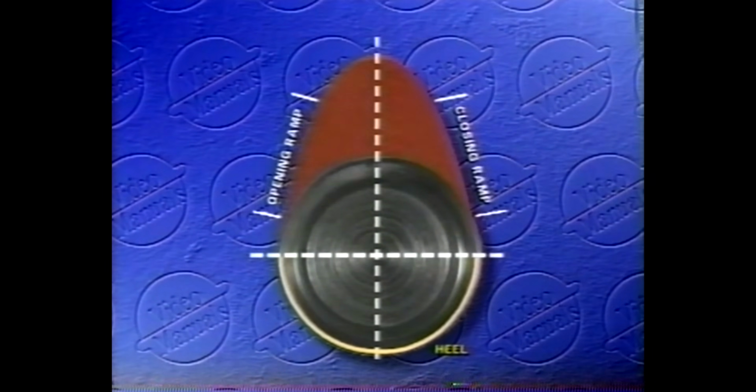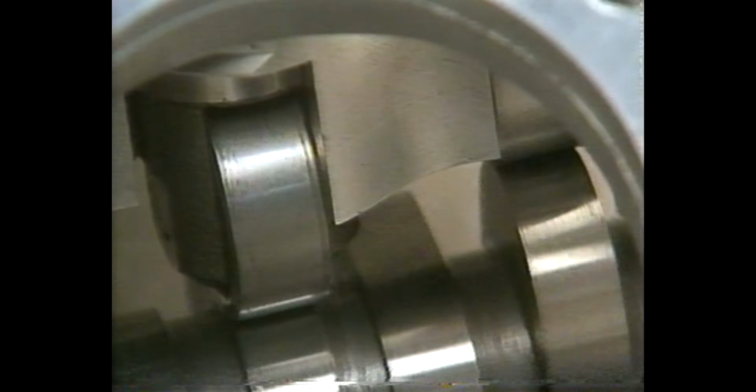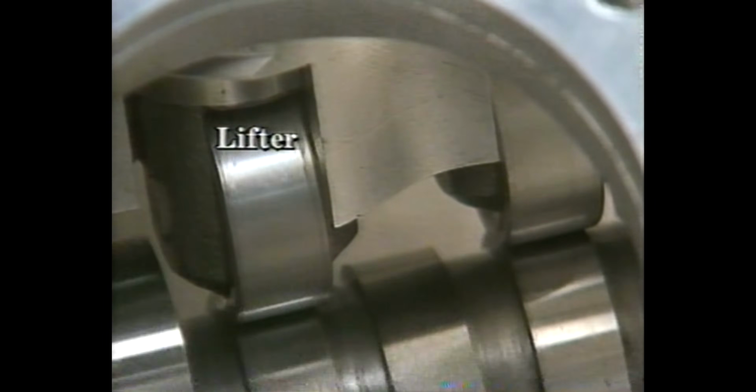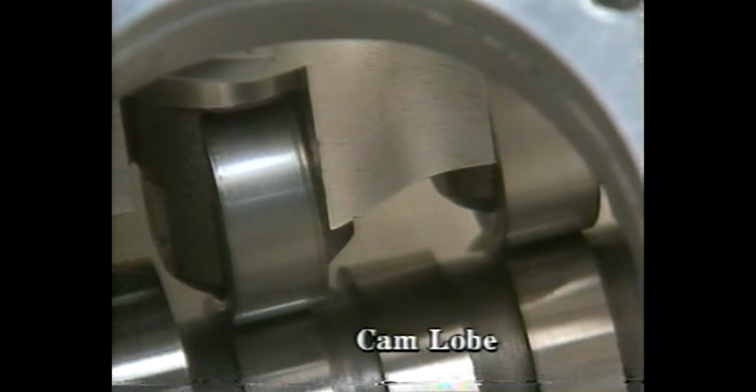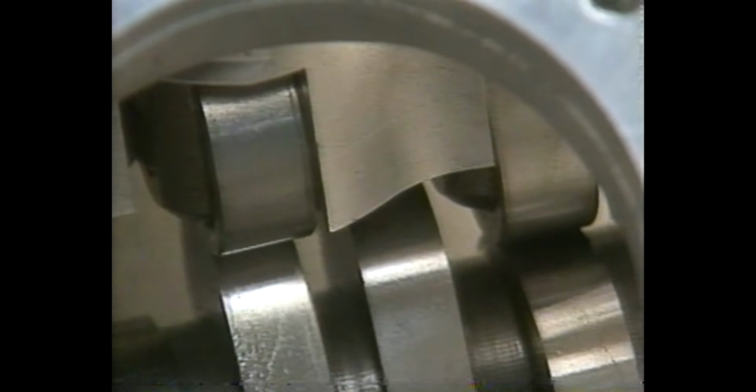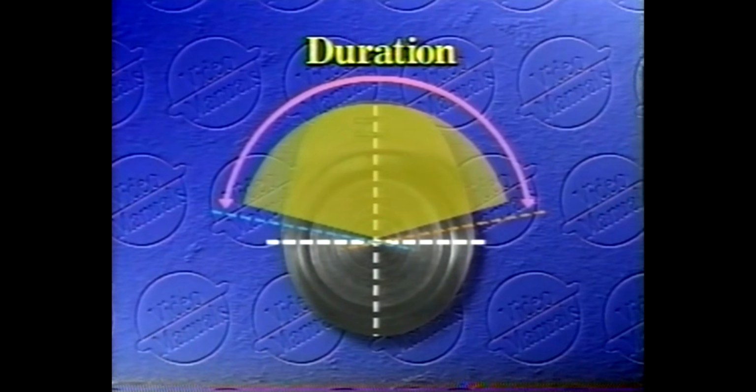Here we have a diagram that outlines the basic physical elements of our camshaft: the base circle, the ramps, and the lobe. The term duration refers to the amount of time it takes the lifter to travel up and over the cam lobe, to once again rest on the camshaft's base circle. Duration is illustrated by the yellow area in this diagram. This time or duration is always measured in crankshaft degrees.